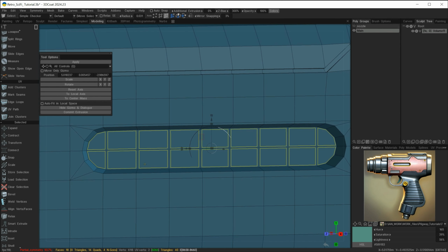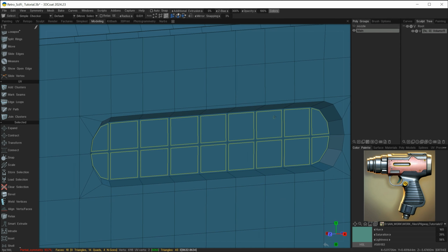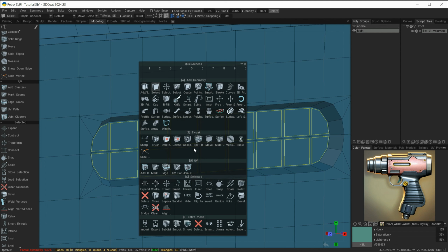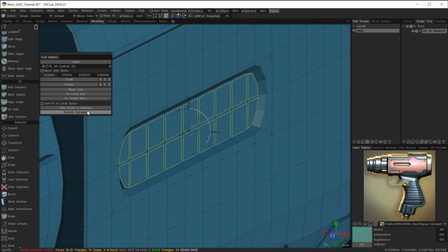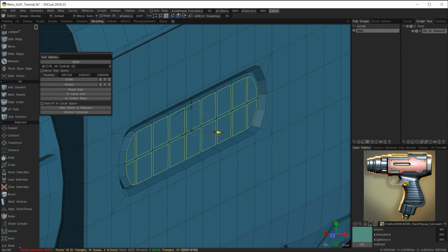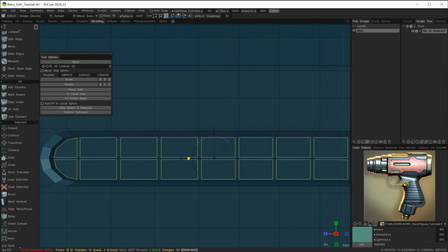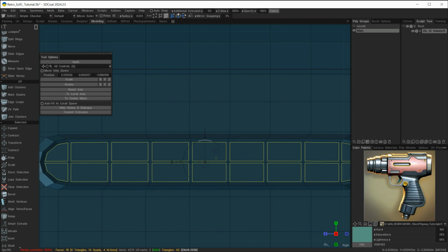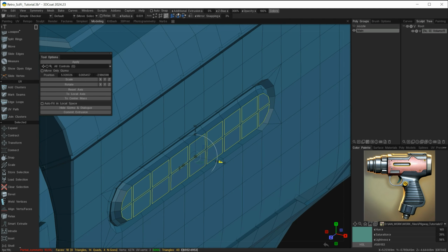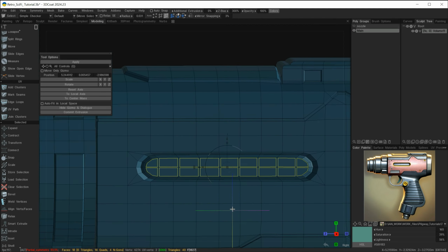And with that still selected here, I will now extrude back out again. So I'll go to my transform tool, extrude. Let's come back out. Let's extrude again. This time I'll shrink this one down a little bit, move it out, just scale it in the Z and the Y, and let's do one more. Something like that.